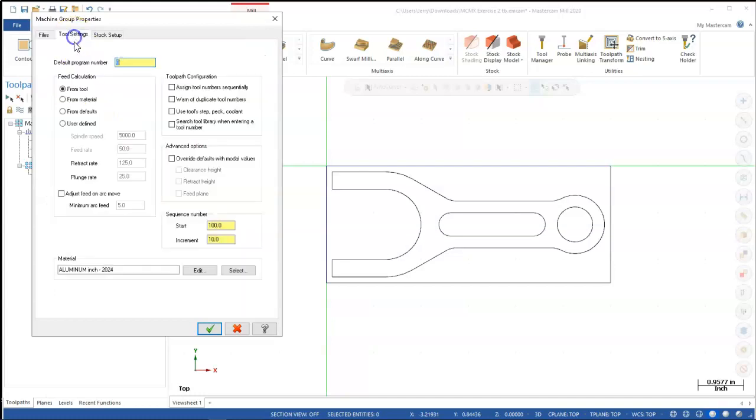When we come over to the tool settings, my default program is 1 or 10 or whatever we want to call it, and it depends on the workflow and the style and how you manage the control. Older controls had the whole 1 megabyte of memory, and if we filled it up with a 3-axis program, we weren't too far away from having to hook up the cable and go DNC, direct numerical control, to run anything above a meg.